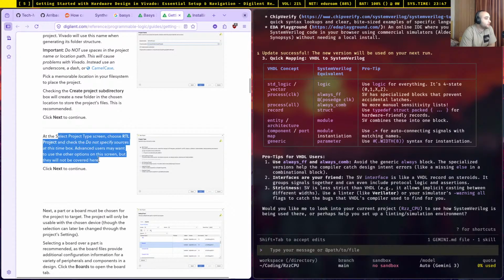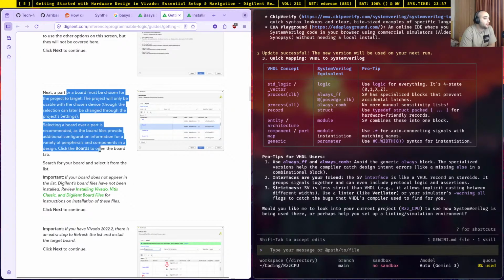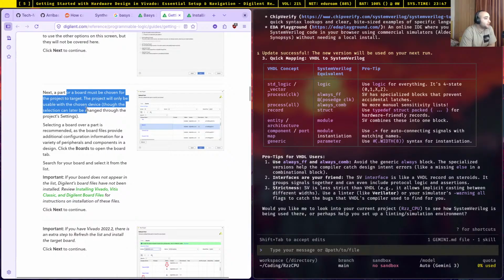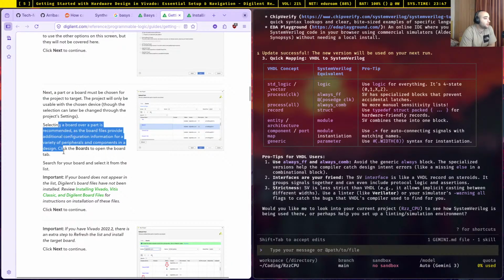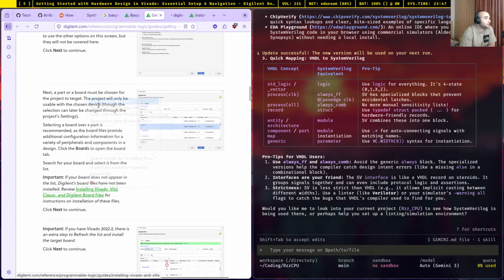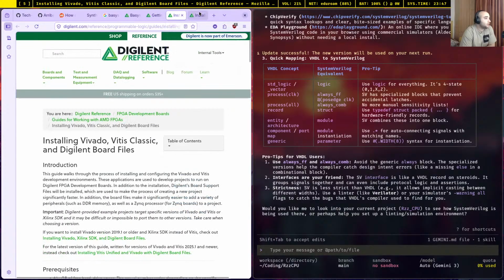Okay. RTL. A partner board must be chosen for the project to target. Yep. If your board does not appear in the list, Digilent board files have not been installed. Okay. Let's do that then.